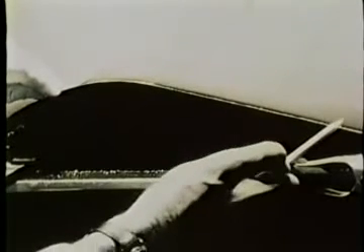Removing the trip rod results in separation and backflow. Bubbles accumulate at the separation point. In this diffuser, which was used before, we have made the bottom boundary layer turbulent by inserting a trip rod upstream. The turbulent boundary layer is able to withstand the adverse pressure gradient in the diffuser, while the laminar layer along the top wall is separated, allowing reverse flow.